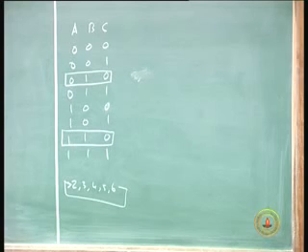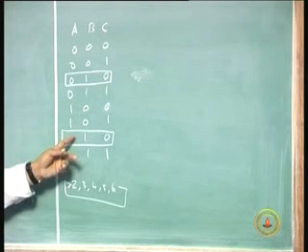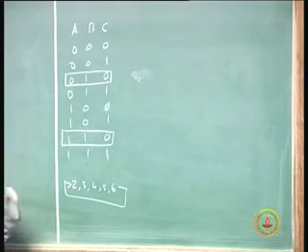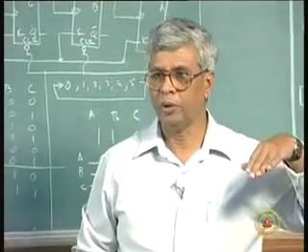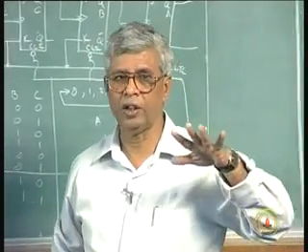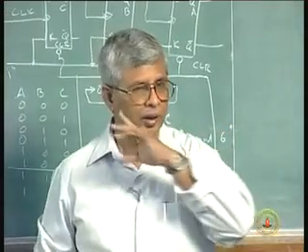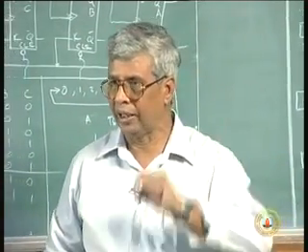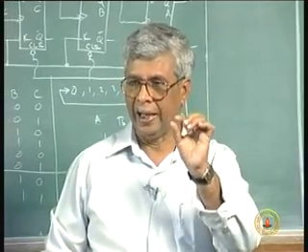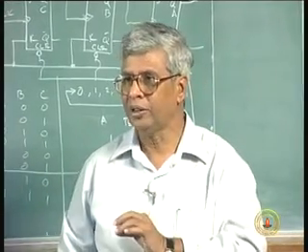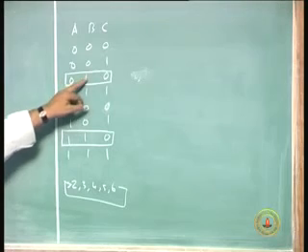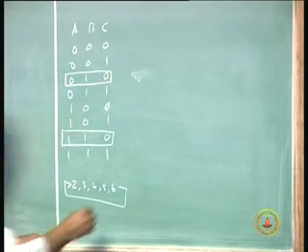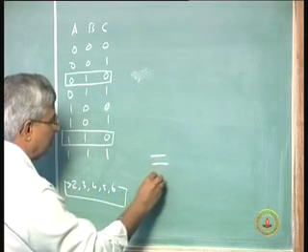So again I do the same thing. I look at 6; I have to complete it. So I cannot detect when the flip-flop reaches the count of 6. I have to wait for count 7 to come up, because 6 has to be completely allowed. So when count 7 comes up, which is 111, I detect that and now, instead of clearing all the flip-flops, I will preset this flip-flop and clear these 2 flip-flops. Correct? So I will get the count 111.